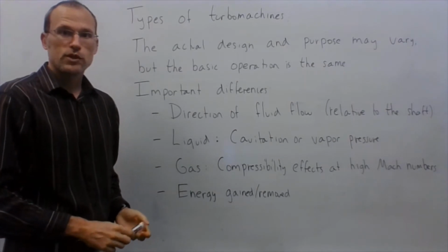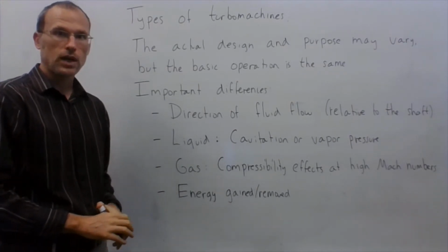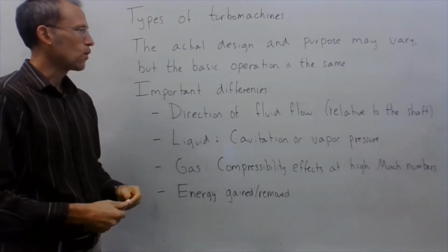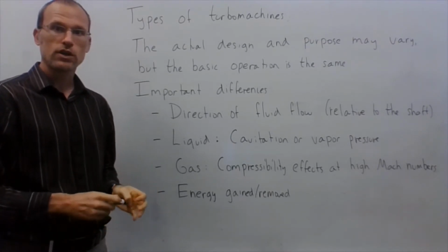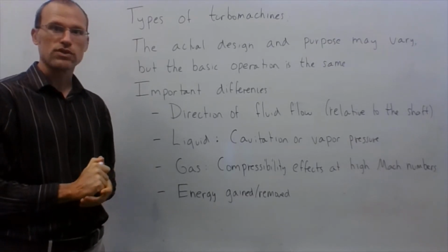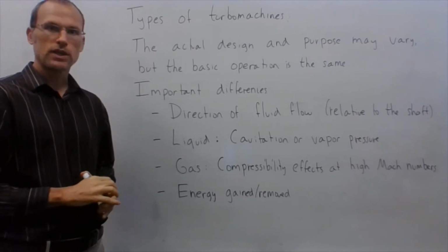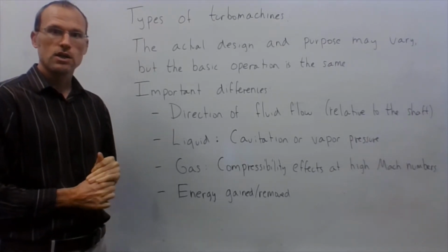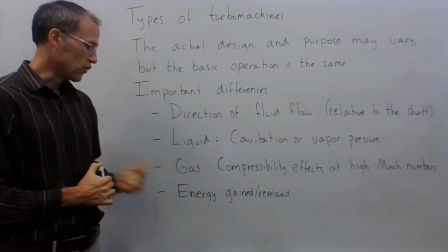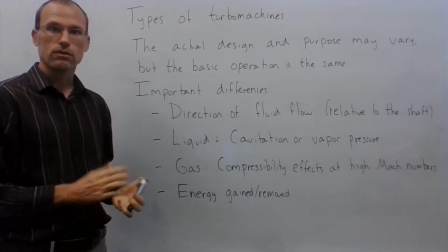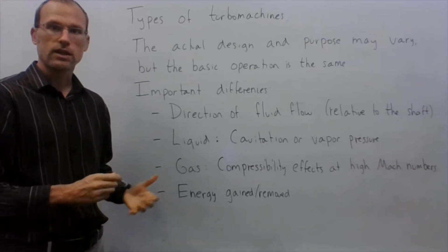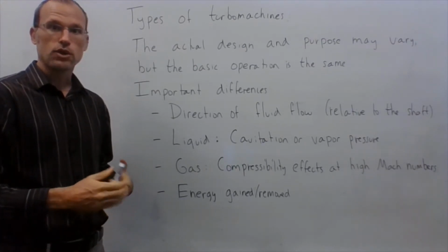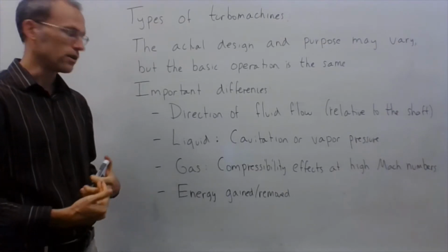So there are many types of turbo machines, as we saw a few minutes ago. These are generally classified based on a few different things. Overall design purpose may vary, but they're all kind of designed with the same principles. And so a few things we need to worry about is which direction the fluid is flowing relative to the shaft. So we'll see a couple of examples of those. Whether energy is being taken away or put into the system. So we saw that again a few minutes ago with the pumps, fans and things putting energy in, whereas the turbines take energy out.